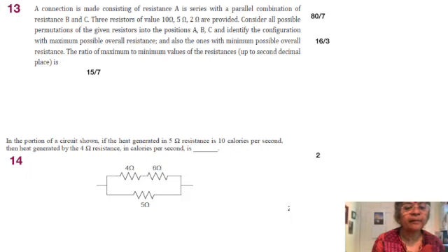And the heat generated by the 4 ohm resistor, which means I by 2 whole square, I square by 4 into 4, is what? So what is I square? That's essentially what is asked. That can be easily obtained from I square into 5 is equal to 10. So it is 2.